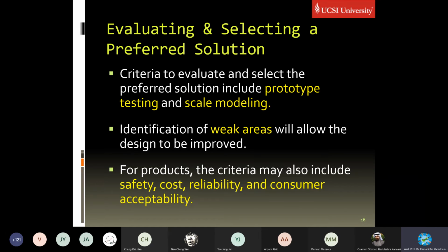And then the scale model that you have used for analysis at the lab. Sometimes if you are analyzing the behavior of an ant, the flies, these small objects, in that case, prototype and scale model are the same. You can call that interchangeably scale or prototype because the proportion is the same. But construction of a dam, construction of a power plant, construction of a building, it involves a scale model, right? In that case, you have to differentiate this scale model from a real structure. Hence, the real structure is called prototype. In some publications, they use even the model as a prototype, tabletop model as a prototype. That's a wrong slang, wrong word.